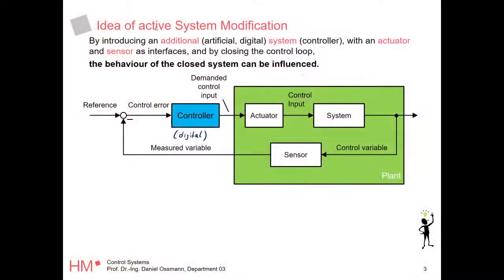I know you have your own lectures for that, so I'm not going to go into much detail about sensors and actuators. For us, sensors and actuators are simply a piece of hardware, and they belong to the plant, right? So, practical example, your aircraft. The system itself is your aircraft. You have an angle of attack measurement, you have a speed measurement, you have a pitot tube. These are your sensors. And as actuators, you have hydraulic cylinders, which steer your elevator, your aileron, your rudder, and so on. Your engines, they are all actuators. From a control perspective, we are all going to stick that into the plant, into the system, right?